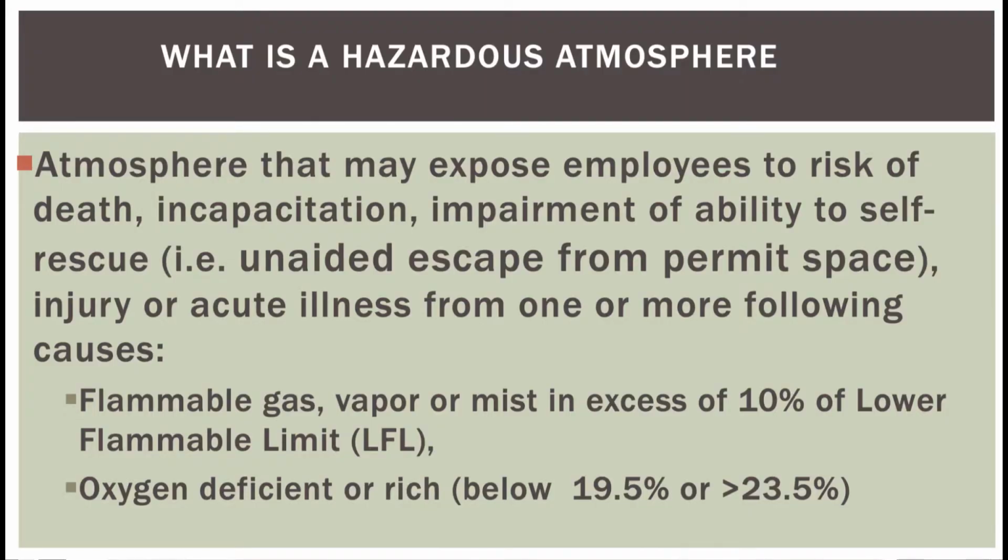So what is a hazardous atmosphere? An atmosphere that may expose employees to the risk of death, incapacitation, impairment of ability to self-rescue, acute illness, and that could be caused by one of the following. So that's flammable gases, vapors, or mists in excess of 10% of the lower flammability or the lower explosive limit, as well as oxygen deficient or oxygen rich atmospheres. So an oxygen deficient atmosphere is below 19.5% oxygen, and an oxygen rich atmosphere is above 23.5% oxygen.